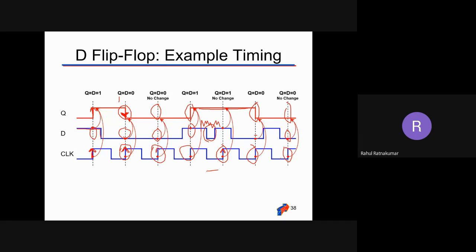So this is called a transparent flip flop. Whatever D is, it goes to Q, so it's called transparent, right? Transparent flip flop, but the only condition is that it acts at the positive edge of the clock. If there is no clock, it will be a latch. So we can say it is a transparent latch. Whatever D is goes to Q. But in a latch, you're acting on the level. I think this concept should be very clear. At all these points of the clock, or your enable signal, your latch is activated. So this is level. But right now it is edge, positive edge or negative edge.